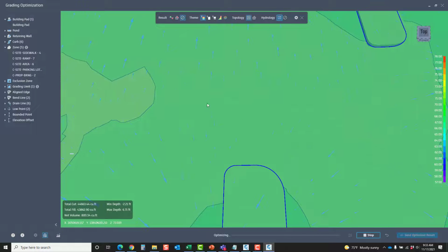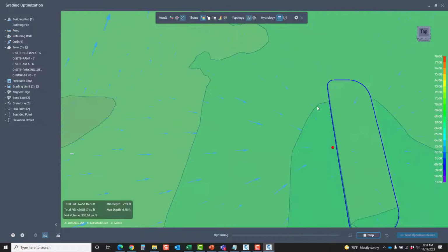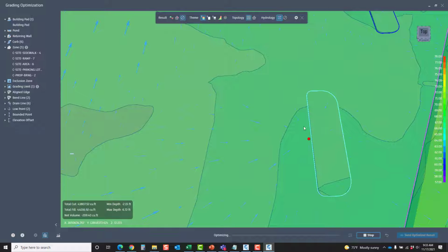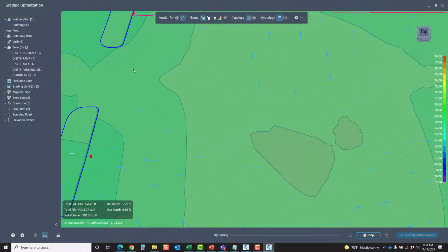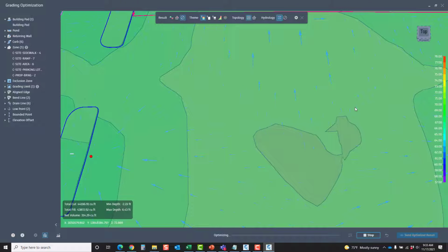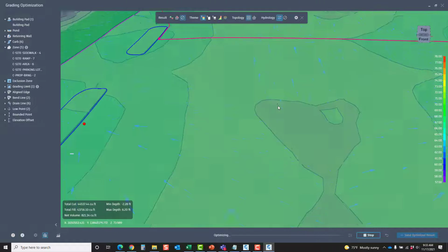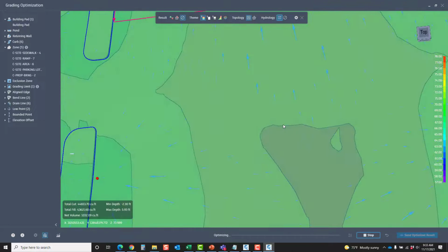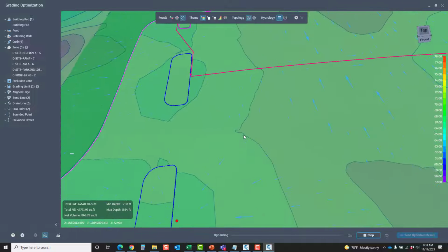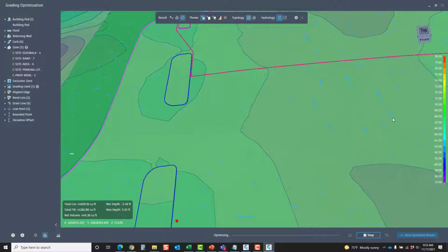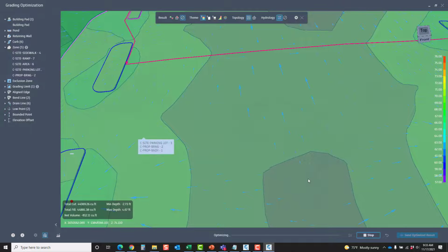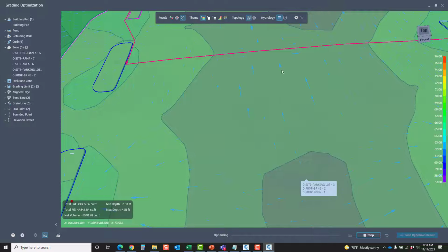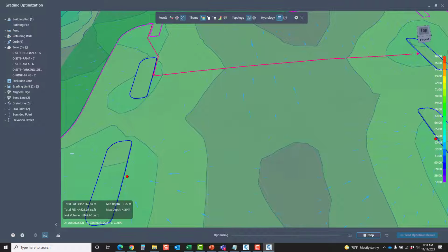And then I have an interface right along here where things start to drain to these low points that I've placed in. So the software is going to figure out where those ridges are and which way the water should break. And it's going to assign those automatically. If I don't like the solution that I see, if anything about it at any point seems to be missing an element, I just stop the process. I go back to Civil 3D, I add a new component, and then I come back in here. I'll see the new element and run it again.